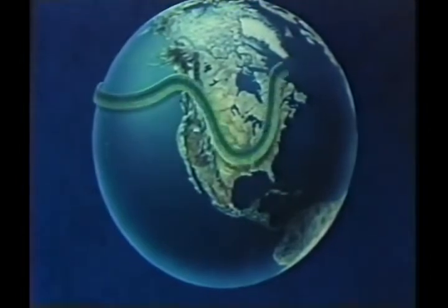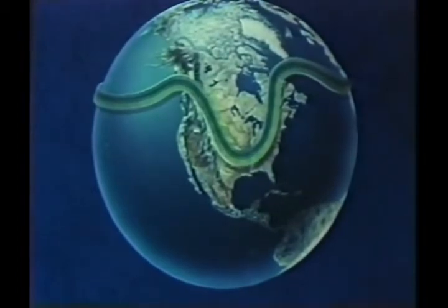Another phenomenon of particular interest to aviators flying at high altitudes is the jet stream, a meandering channel of high-velocity wind generally found between 15,000 and 40,000 feet. Its altitude varies along its course, which is usually west to east, though not always direct. In it, wind speeds of 150 to 200 miles per hour and even greater have been encountered. It is a terrific booster going east. Going west, avoid it.